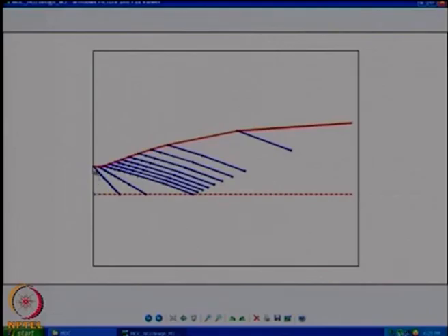So from here I go along the characteristic, some delta y downward, and then I will find the next point there, some delta y downward. I just divided this throat height by 10 points, so I will get 9 delta y's here. From there to here I moved that height down along the characteristic, found the exact location from the transonic solution there. I will get my theta and M values there.